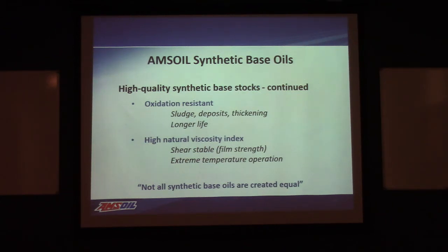Natural high viscosity indices, so we know right off the bat they're going to have an ability to function over a broader temperature range and protect over that broader temperature range. They're not going to thin out at high temperatures when the going gets tough and lose their ability to carry a load. Big takeaway here: not all synthetic oils are created equal.